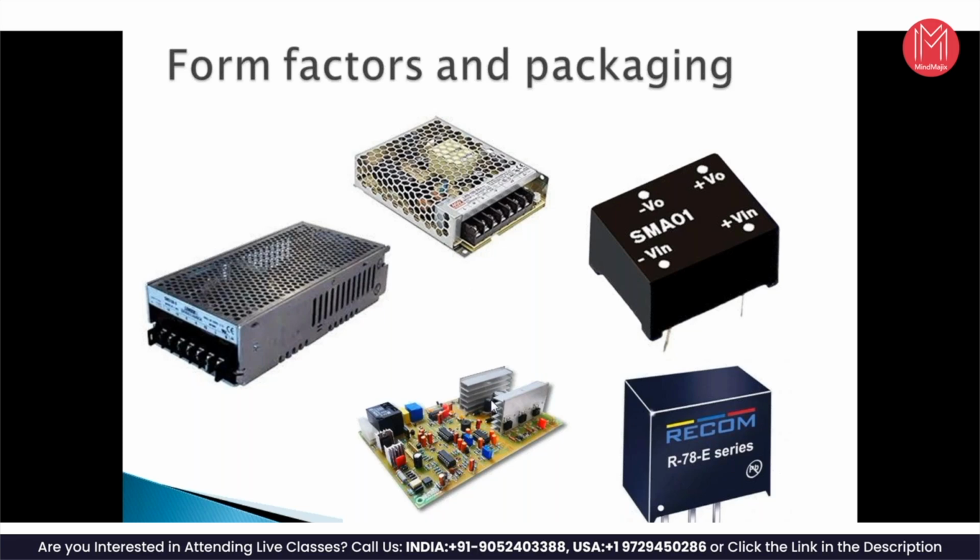And if you have a further smaller device, these are really of the size of 2 centimeters, and this complete power supply takes AC mains and converts it into the required DC voltage, 9 volts or whatever. This can be directly soldered onto the PCB, and it is about 2 centimeters by 2 centimeters by 1 centimeter in size. Whereas this power supply is about 8 centimeters by 8 centimeters by 3 centimeters.